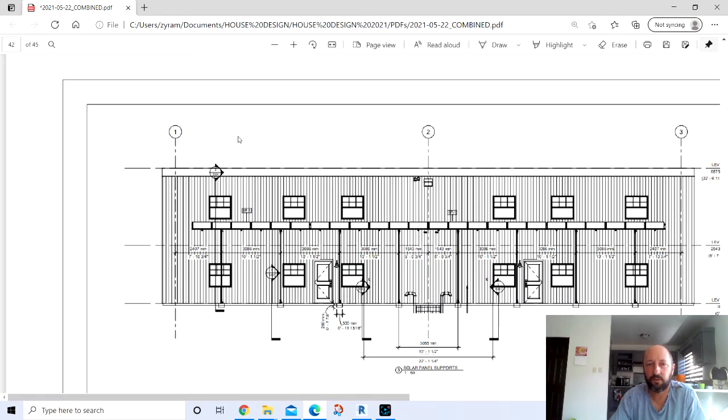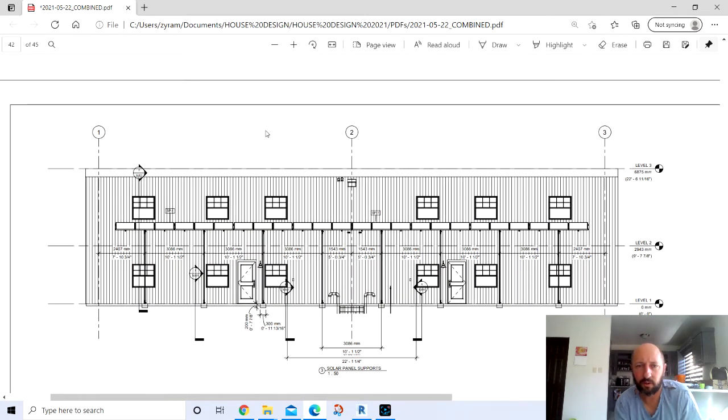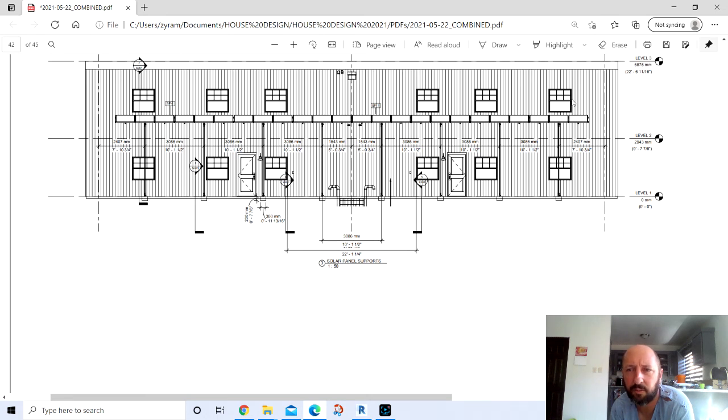This is a section view of the solar panels. You can see up here where we got the wall packs, and then we mounted our CCTV right below the solar panels in order to protect them from the weather some. That's another purpose for the solar panels here, is that'll create like a porch area. I'll put flashing in between all the panels so that they block most of the rain coming down, and that way you'll have a kind of a makeshift porch on the front if you'd like.